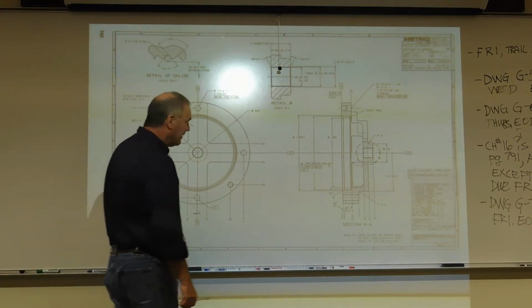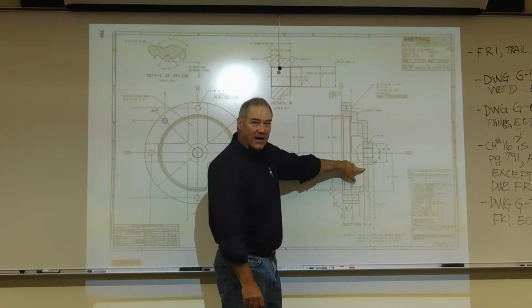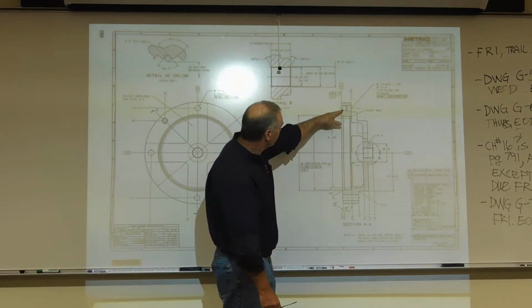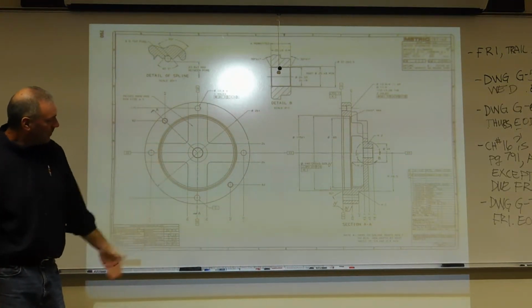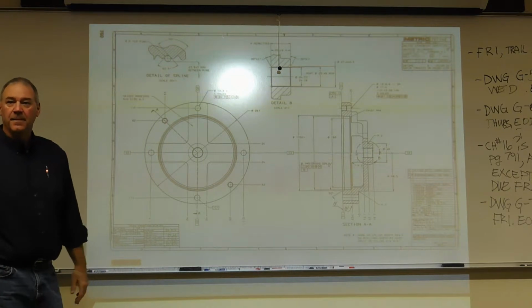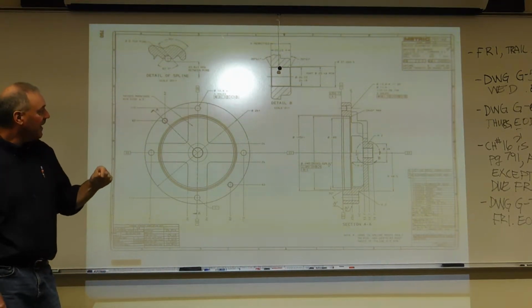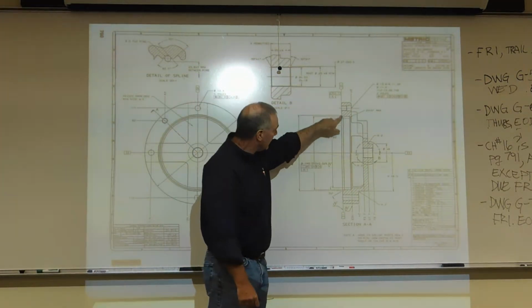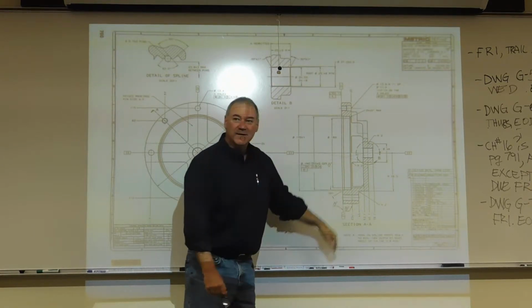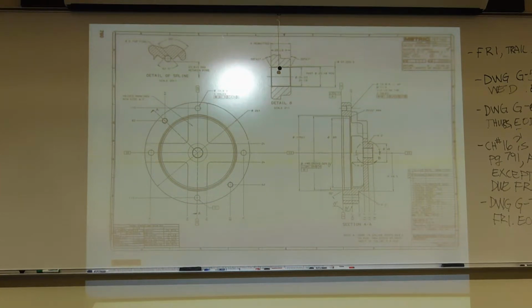Now, once we do that, we start seeing all these interior features, and our object lines are describing this inner plate with the holes through it that we got with different shoulders, because we got a counterbore hole on top, through hole in the middle, through hole on the bottom. And we see all those nice object lines, they stand out versus all hidden lines. You can imagine what this thing would look like with hidden lines all through here and these buried, and it'd be a mess. So in essence, cutting the object open to reveal interior features.